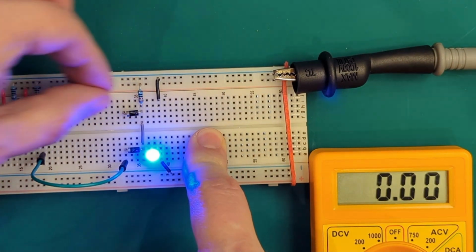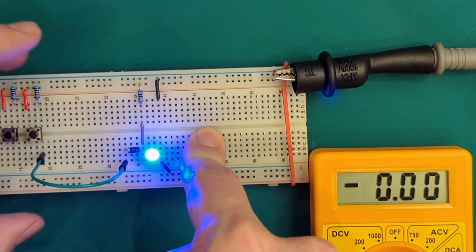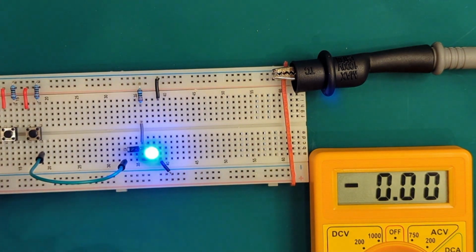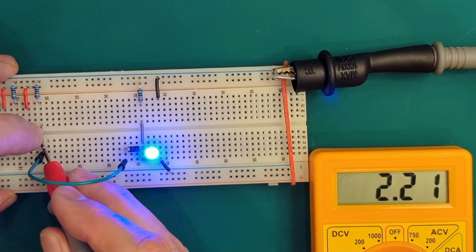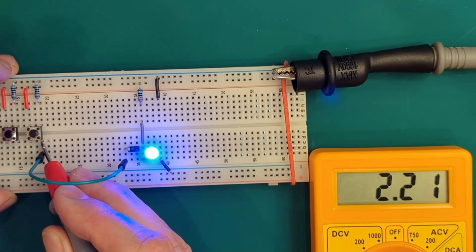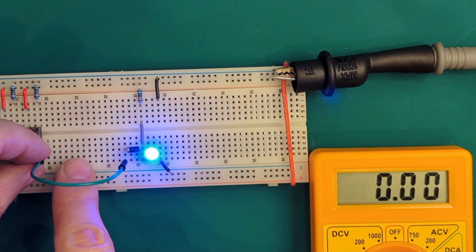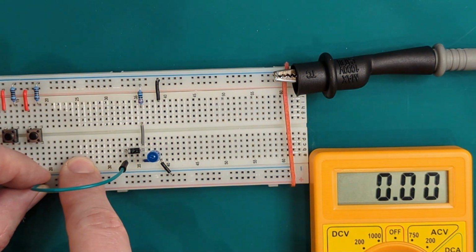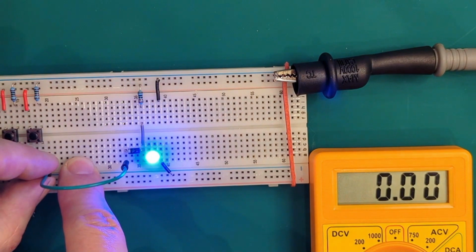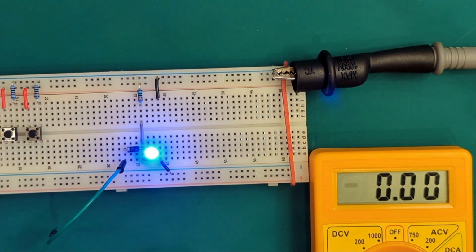So I'll remove this, I'll remove this, and now we have only one button. And if I measure here, I'm still getting 2.2 for the unpressed button. As you can see, we still have the same issue. That means that my low values for the button are pretty bad, 2.2 volts rather than 0 volts. And if I put the gate into a real 0 volts, it actually works fine. And the button by itself actually did work.